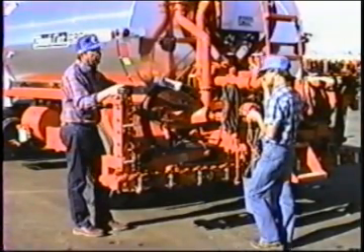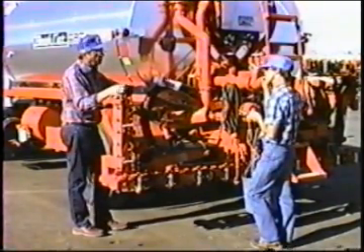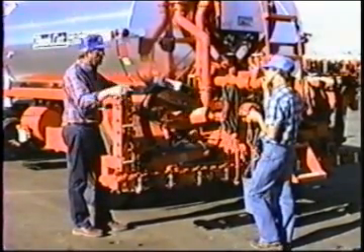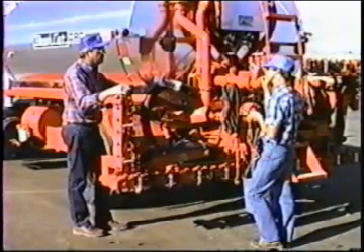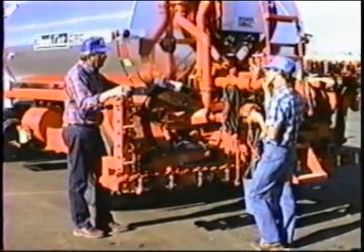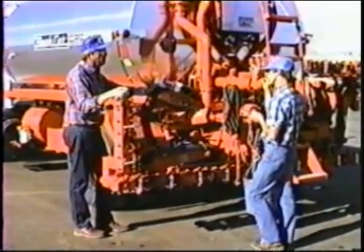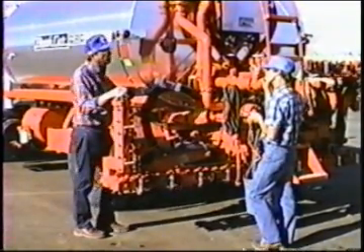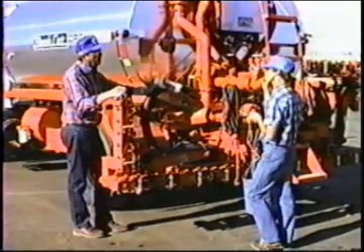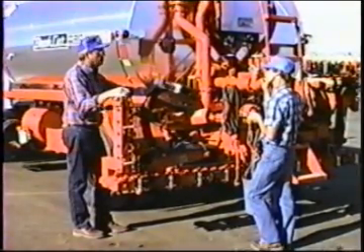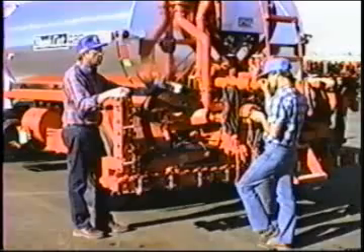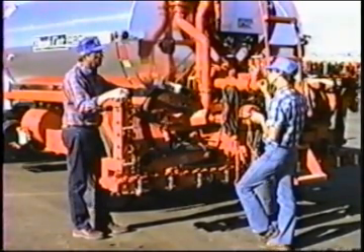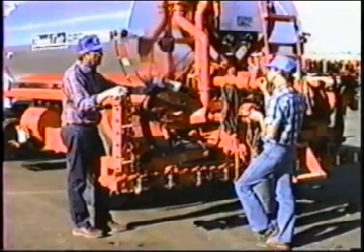If you work above 12 pounds, you're going to create a lot of overspray. That is, you're pushing the material out of the nozzle so hard that it atomizes, creates a lot of overspray, and that gets this fancy machine all dirty. If you keep your pressure down around 8 pounds, then it all goes on the ground instead of all over the truck. So we're going to emphasize that you work at low pressures, somewhere between 4 and 12, ideally somewhere around 8.